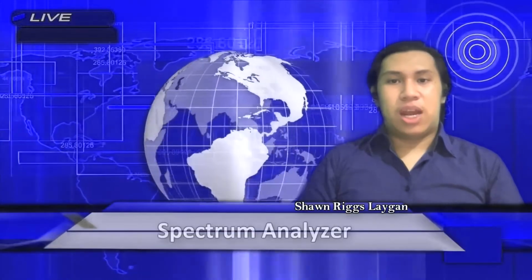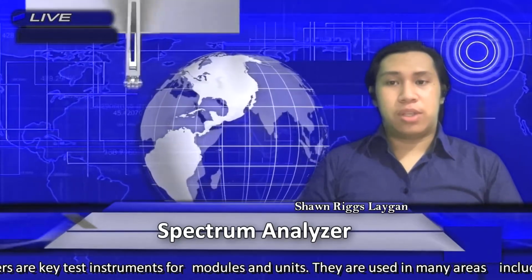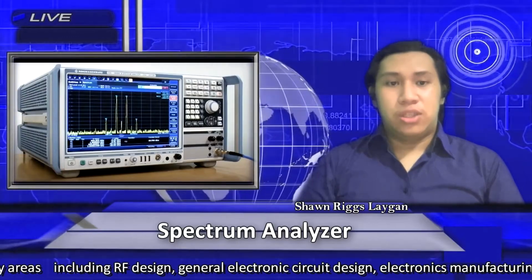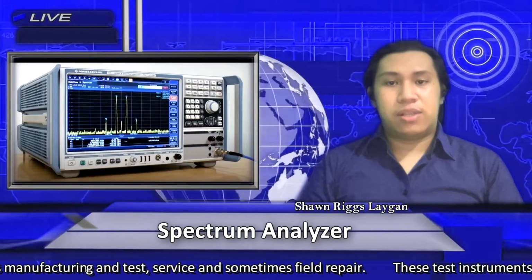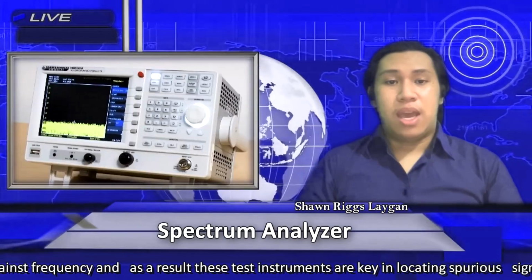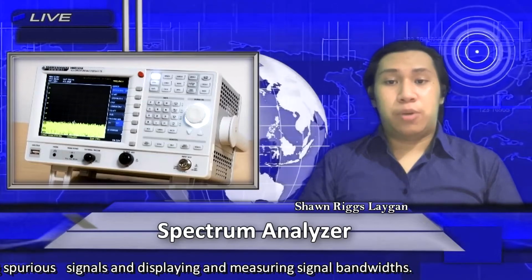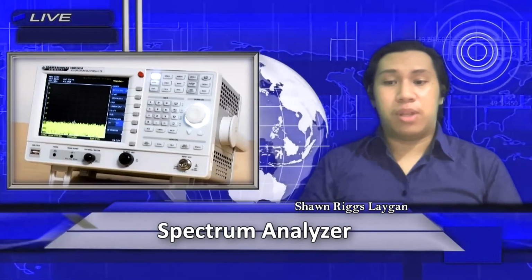Spectrum analyzers are key test instruments for use when testing radio frequency, RF circuits, modules, and units. They are used in many areas, including RF design, general electronic circuit design, electronic manufacturing, and test, service, and sometimes in field repair. These test instruments display amplitude against frequency, and as a result, they are key in locating spurious signals and displaying and measuring signal bandwidth.